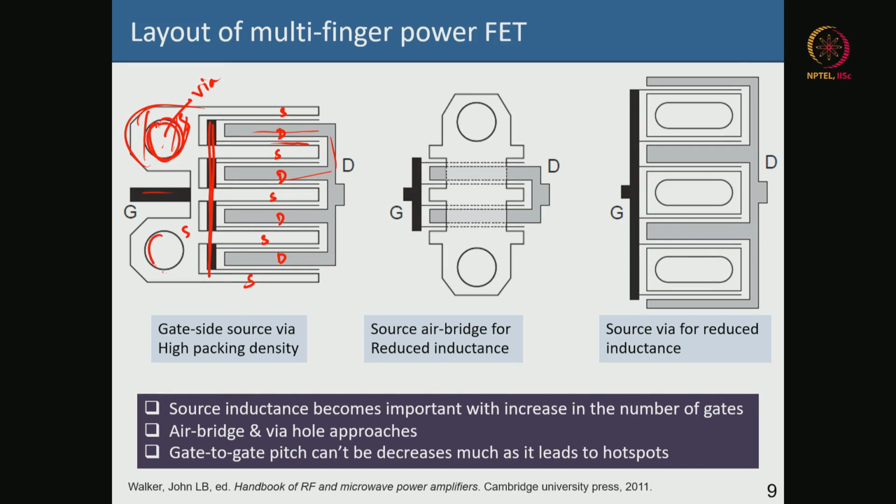So, this via hole connects the top source, which is grounded, to the back side, which is also a metallic plane. It is a low inductance ground plane. So, the source is connected metallically to the ground plane below, and it reduces the source inductance L, as opposed to using wires; you are directly grounding the source to the backside ground plane.